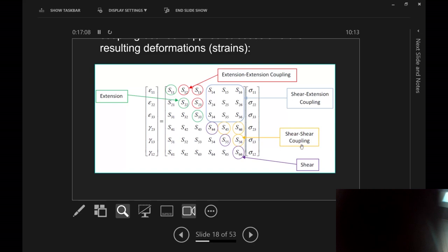When it goes up, it also twists, so it increases the lift, but probably twists this way to reduce the aerodynamic load. You can't achieve this with metallics, but with composites, it not only goes up, it twists as well, just because of bending. The loading is not changing, but the behavior becomes different. We're not using this for any aircraft at the moment, but there's a lot of research going on.